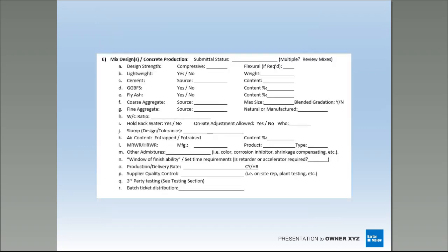Now we're going to get a little bit more into detail when we get into the mix designs. All right, this you really got to focus in on, right? Your compressive strength. I like to see 4,000 psi on just about everything. It's going to be over-designed anyway, and you're probably going to break around 5,500, which is a good break. Some are way over-designed, and I've seen some slab mixes that sit over 28 days and they're breaking at 7,000 psi. This is when you need to sit with your concrete supplier in that meeting and get a break history